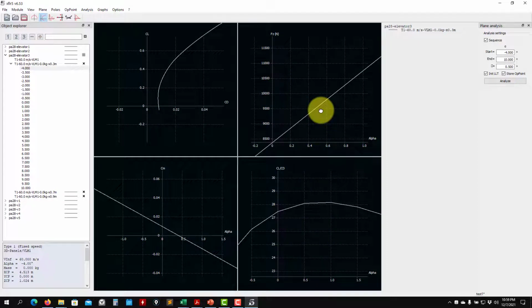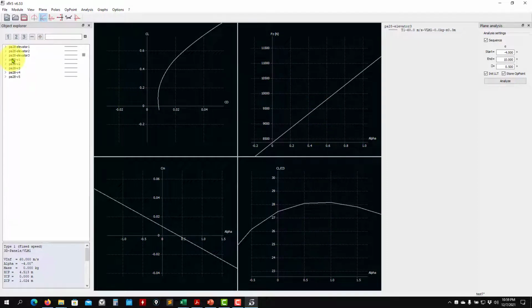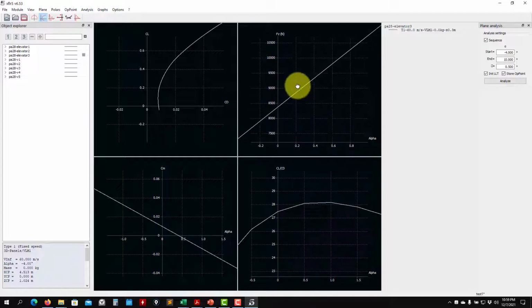So we designed only the wing, and then we added the tail using, remember in the tail, we cannot use the LLT method. You need to use vortex lattice or panel methods. As you see, it's very fast. Now imagine running all these cases using CFD. If you haven't done CFD, you will see later that it's very time consuming. Or even if you do experiments, it can be very expensive. So this is the advantage of these methods.